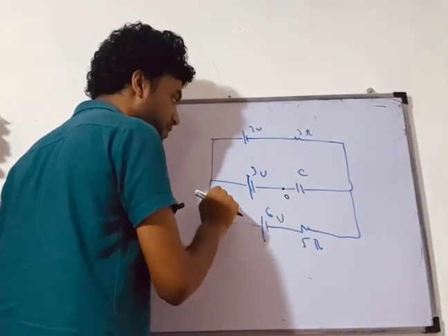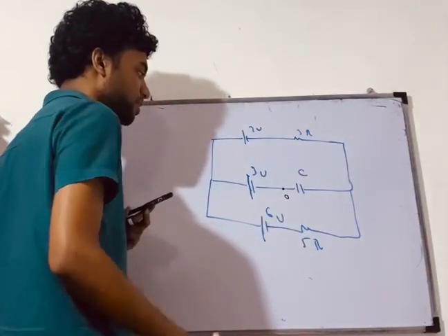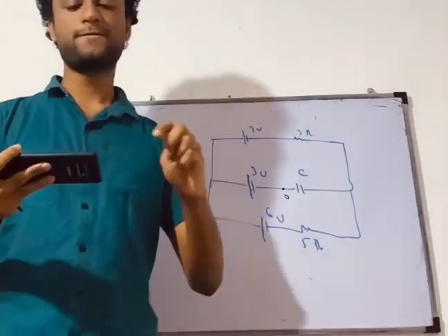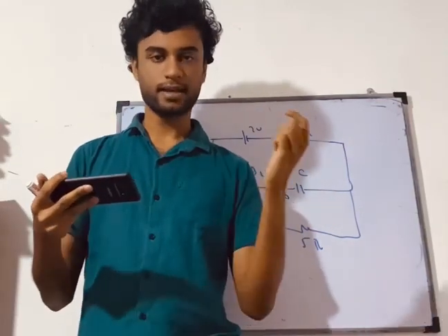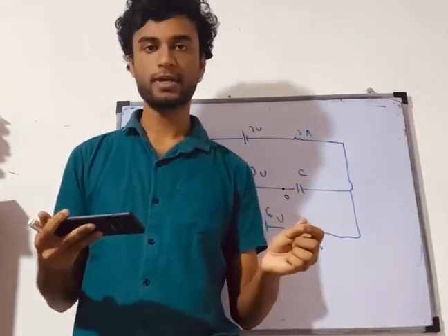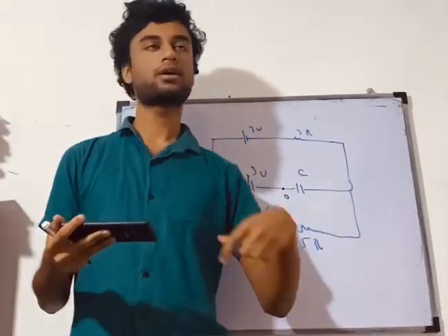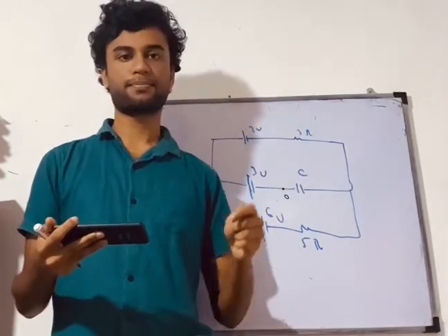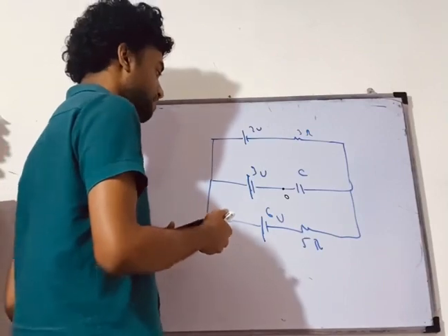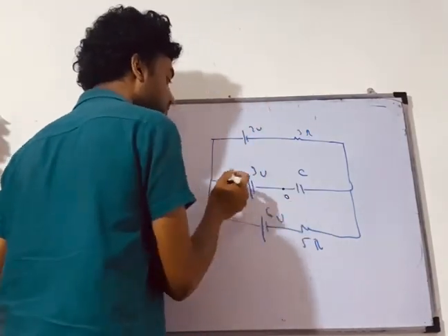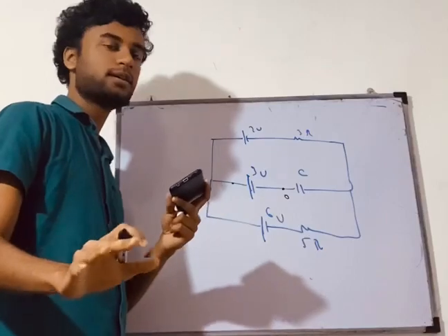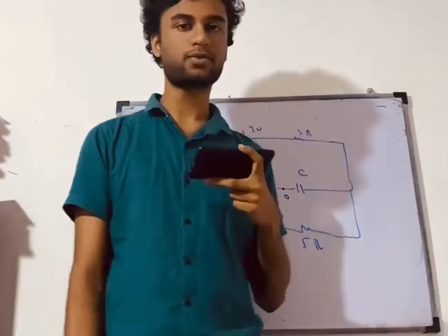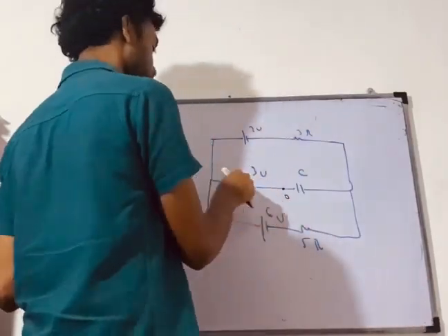Now we know the potential difference across this is going to be 3 volts. But listen, if you consider a capacitor like this at steady state, which means there's no current flow. So when the capacitor is at steady state, there's no current flowing through it. Once it has been charged, there's no current flow. Right? So here, if the potential here is 0, is everybody clear that the potential here should be plus 3? Because the potential difference will be 3 volts for the battery. Then if I have 0 here, I should have plus 3 here.